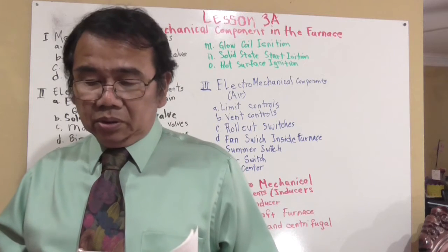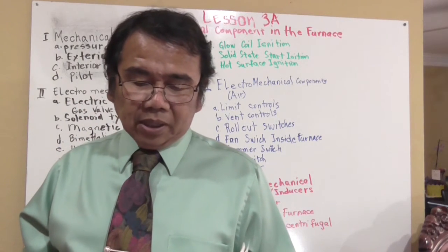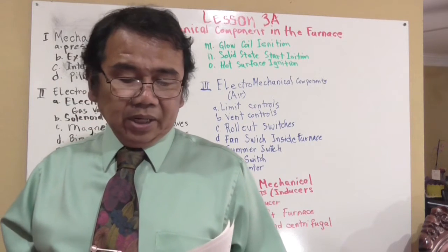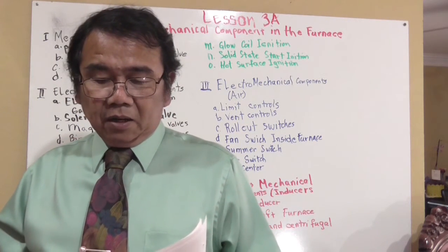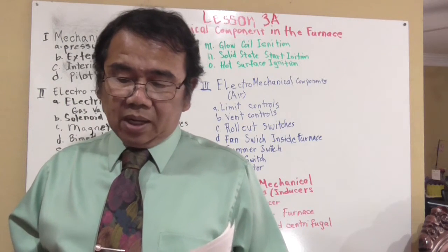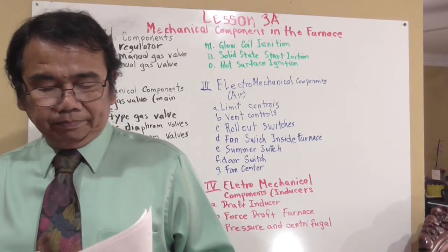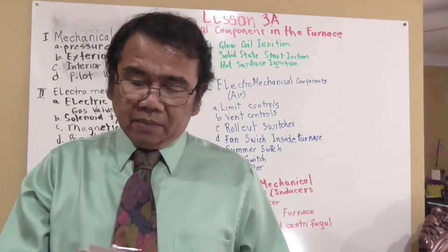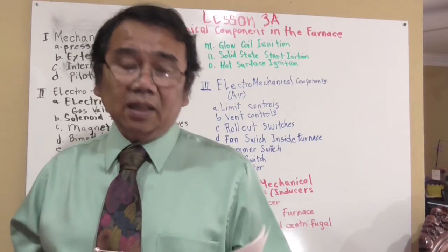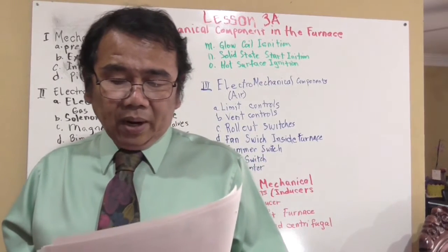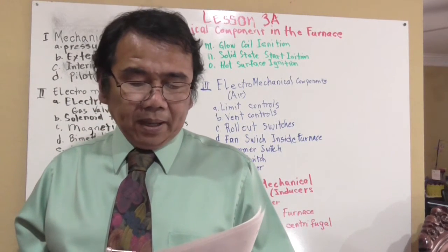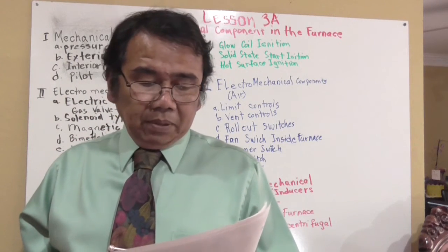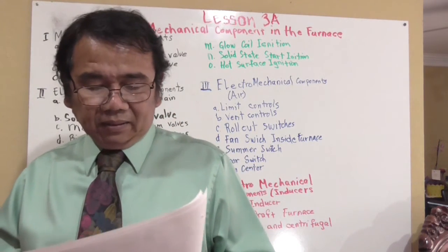When the switch closes, the W wire from the thermostat will then be allowed to energize the gas valve, providing no limit switches are open. If the equipment is using a pressure switch proving device, that W wire from the thermostat must pass through the normally open pressure switch before energizing the gas valve.